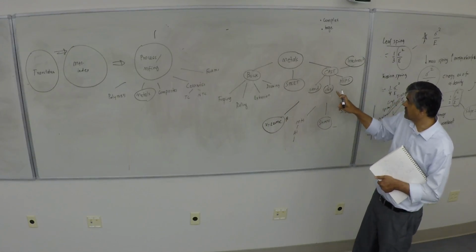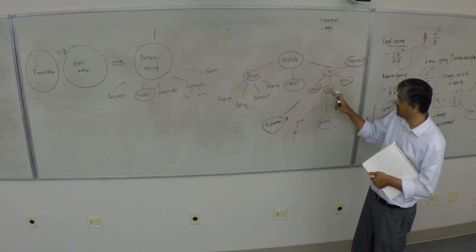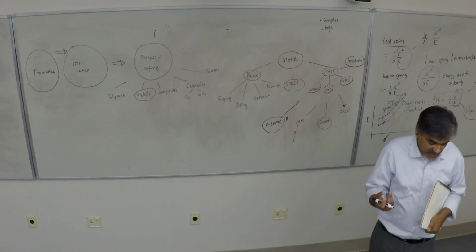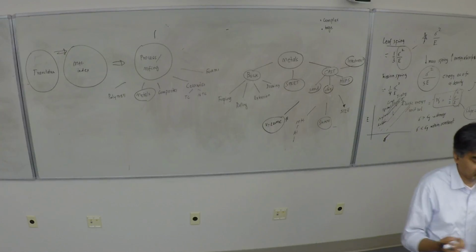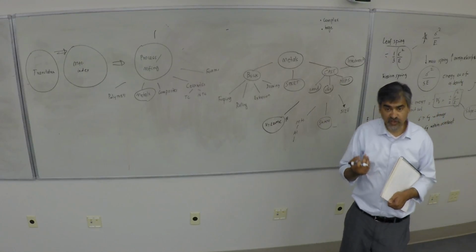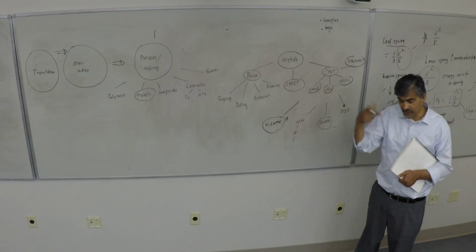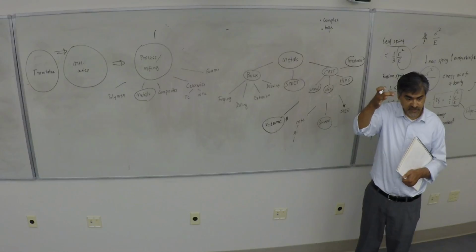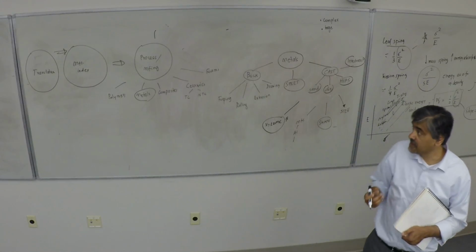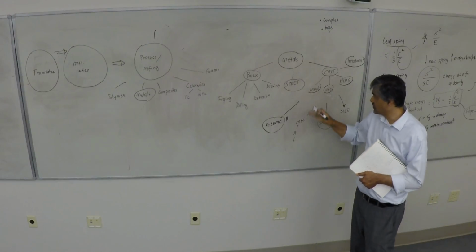When you look at casting, it's a very different family, it's very flow dependent. So the rheology of the metal, the trapped voids in the metal, a lot of impurities that can get trapped in. So all those factors, and then turbulent flow once it enters the die. When you send it through the risers and the gates, the material in the die has to flow a certain way.